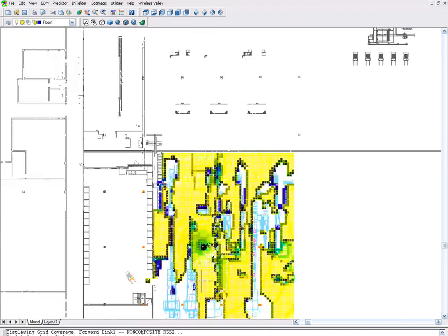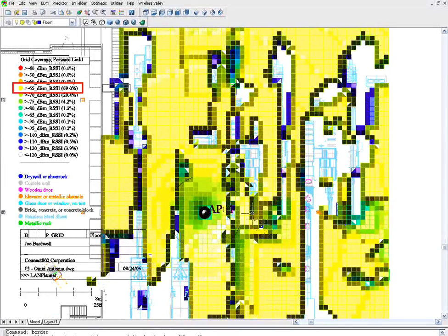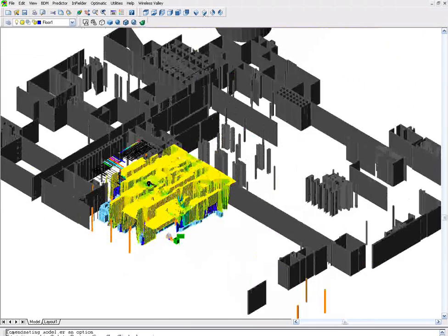By looking at the legend on the left-hand side of the page, we can see that yellow at minus 65 dBm is better coverage than the green areas at minus 70 or minus 75 dBm. And directly below the antenna, there's the green, weaker coverage area on the floor of the plant. When areas like this are observed in the predictive design, we might want to go on-site and pay more careful attention to those specific areas in a large plant facility.